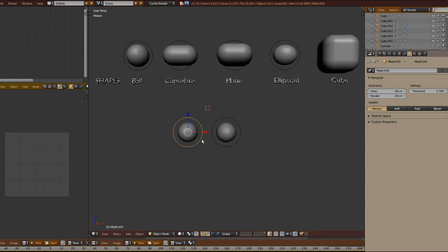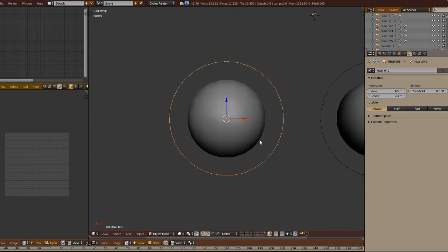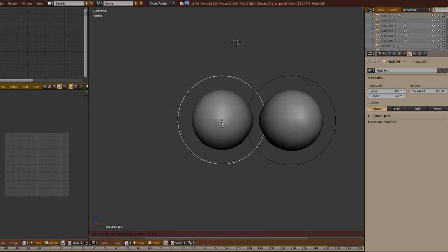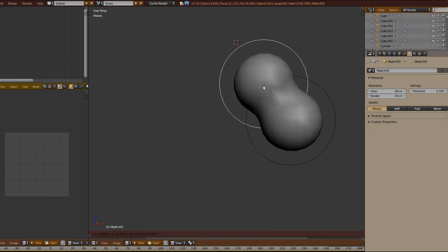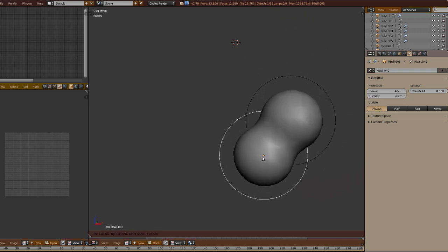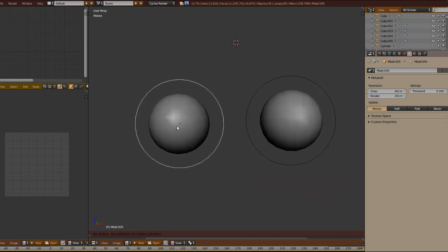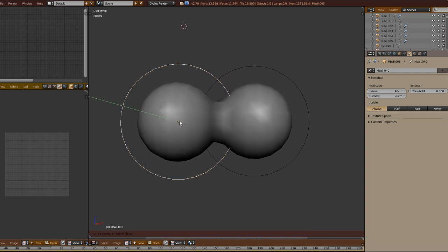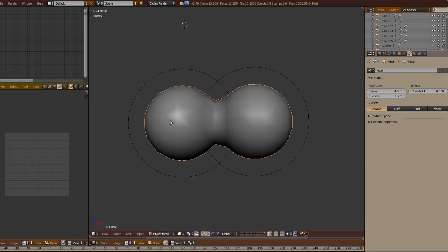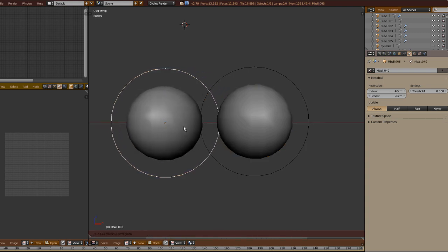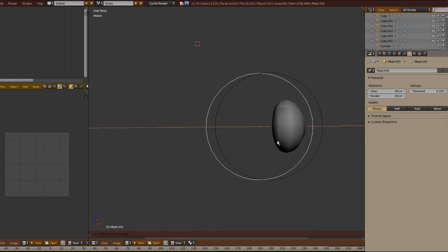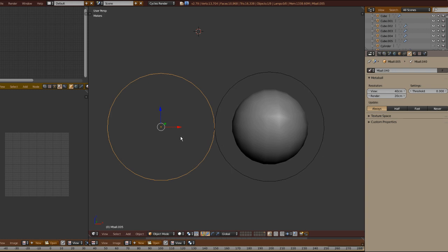The first is the metaball system, which is a powerful system of creating mesh by a non-destructive process. Metaballs are objects created from mathematical formulas calculated in real time that have characteristics that simulate a mercurial fluid. When 2 metaball objects are close to each other and according to the area of influence, they attract and begin to merge. Metaballs can have 2 Boolean operations, addition and subtraction, that can be changed at any time.